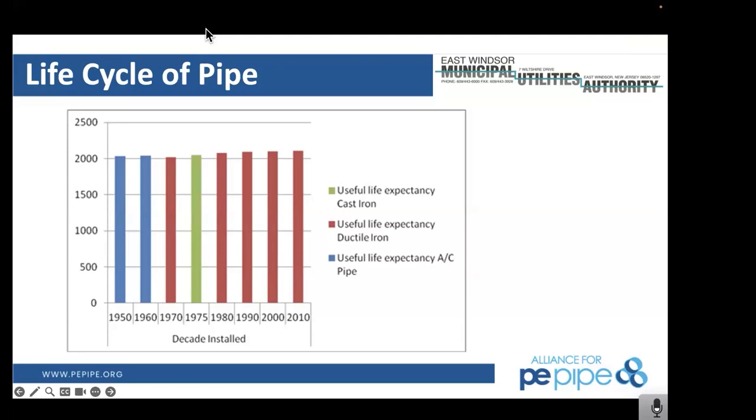Number one, you have to make sure the contractors, when they're installing it, are handling it with care. Most of the time they're not. It's all about time: let's get it in. What happens is the bags get ripped or torn, and they're not secured, so then you get leakage.